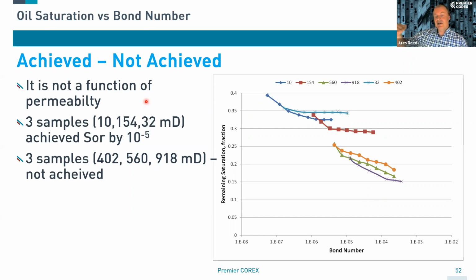As you go through the transition zone, your connate water saturation, this is how I view connate, could be reducing from 1 towards irreducible or towards initial. So connate really just means the value that is there at that layer, at that depth of the reservoir, or that height above the free water level.